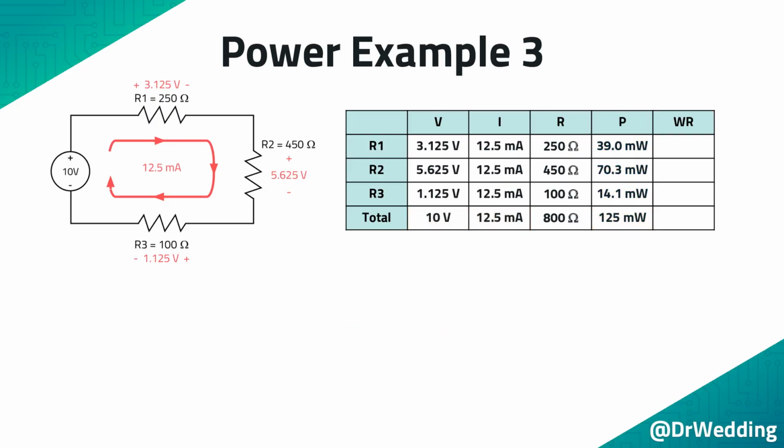Using the calculated power, you will need to select the correct size resistor to prevent it from being destroyed by heat. Note, different books, different instructors, and different employers may perform the next step differently. In this video series, I will assume a safety factor of 2. This means I will use the smallest wattage rating that can handle twice the power delivered to the resistor.